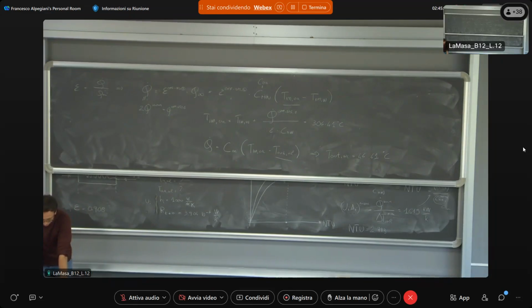The convective heat transfer coefficient between water and tubes wall can be estimated by means of the Dittus-Boelter equation, which is given in the text, also with the parameters n and so on. Then it is given that Nusselt and Reynolds numbers are referred to the internal diameter of the tubes, and it is given that to solve the exercise, neglect the variation of the thermophysical properties, viscosity, thermal conductivity, and specific heat of